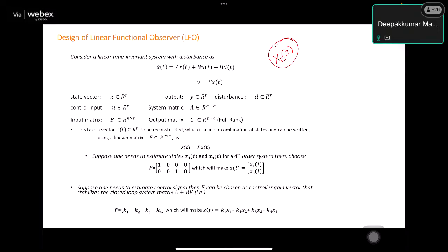The system is fourth order. I can have a first order observer which can only estimate x2 hat. I can also design a first order observer which can only estimate u hat(t). That is not possible with other classical observers, and also many variants of this observer, because there are a large number of observers that exist, and with all of them it is not possible to estimate. You will have a higher order observer compared to what you get from the functional observer. So that is one advantage of the functional observer.